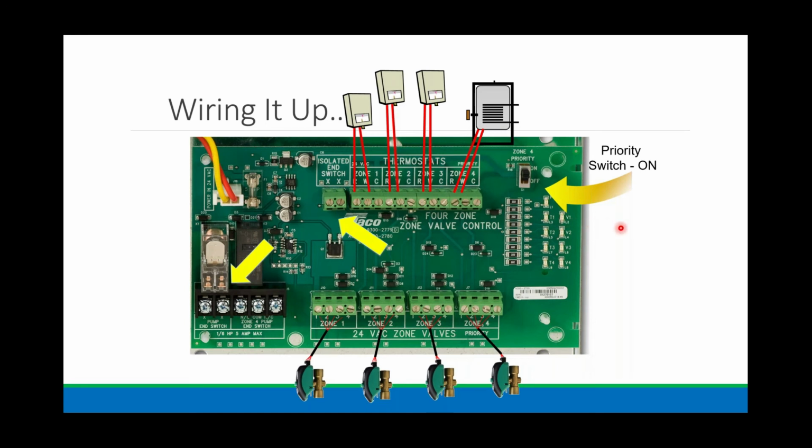So if you're on the job and zone number 2 is not working, well, do I have power? If I've got a green light, we've got power at the board, so we save you time there. Is the thermostat good? Well, yeah, we've got a yellow light, but the red light didn't light up. What's that telling you? There's something wrong with the zone valve motor. So you've really taken a lot of troubleshooting time and dramatically made it so much simpler for all your techs. The wiring is so simple, and the troubleshooting is very simple.